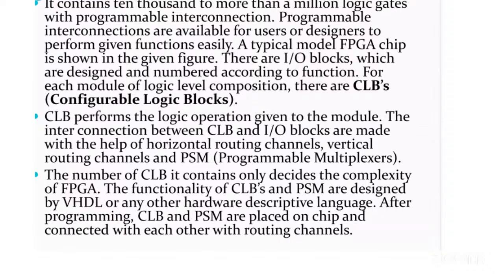The interconnection between CLB and I/O input-output blocks are made with the help of horizontal routing channels, vertical routing channels, and PSM, programmable switch matrices. The number of CLBs it contains decides the complexity of the FPGA.